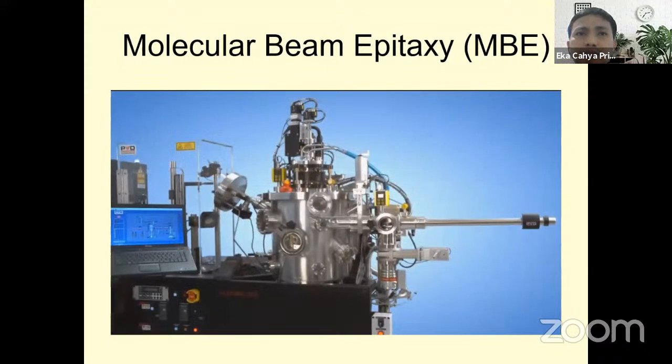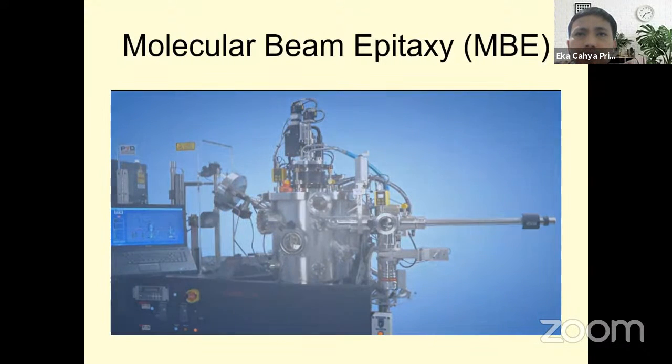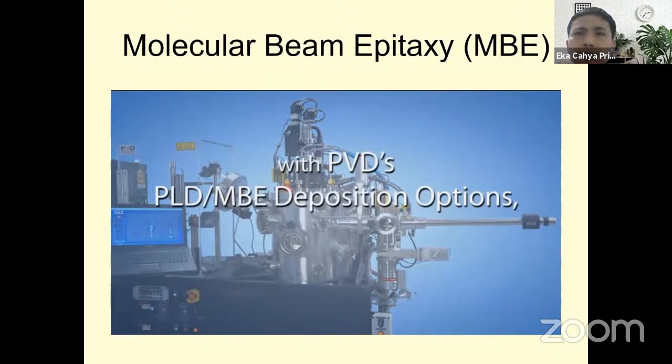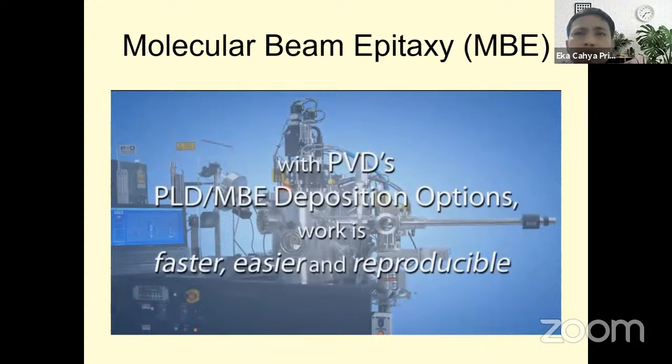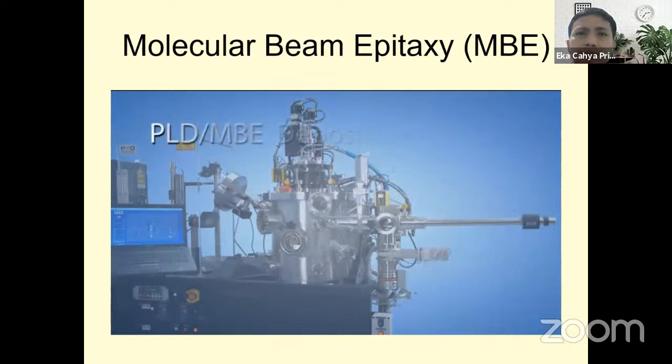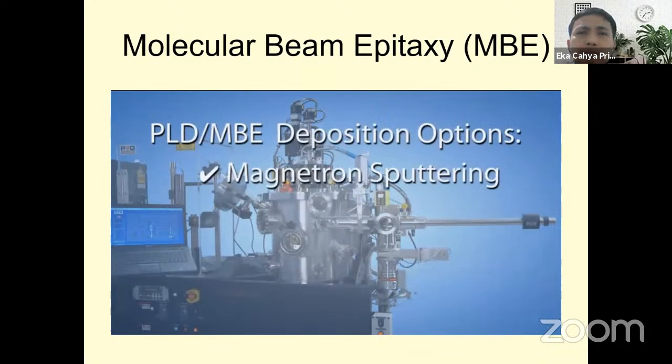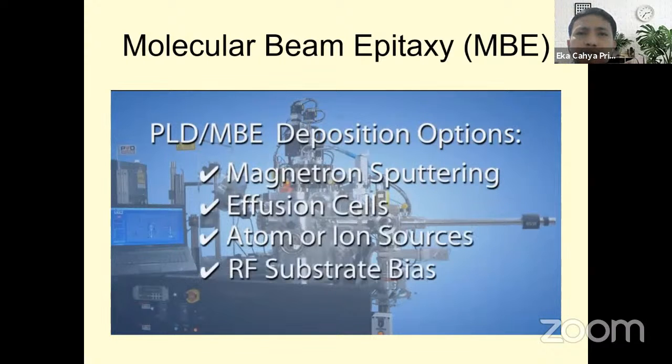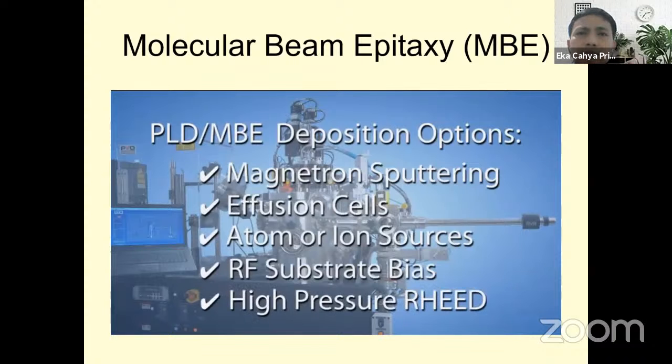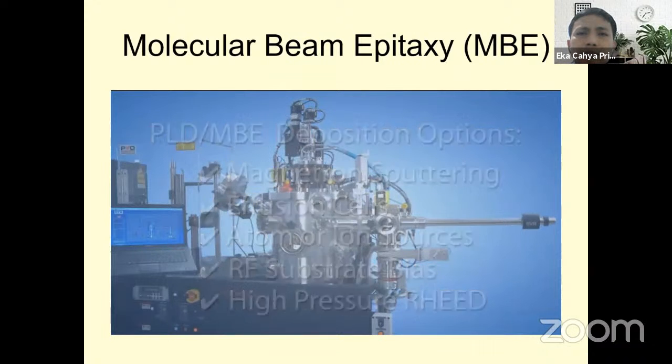Our PLD MBE deposition options allow you to complete multiple types of depositions all within one chamber, making your work faster, easier, and reproducible. Deposition options include magnetron sputtering, effusion cells, atom or ion sources, RF substrate bias, and high-pressure